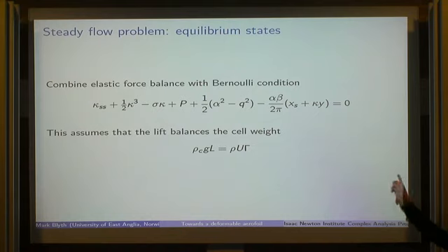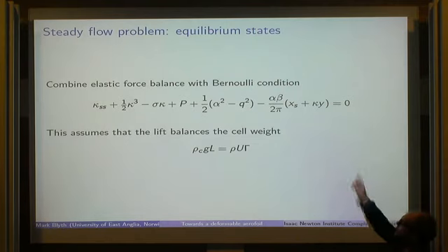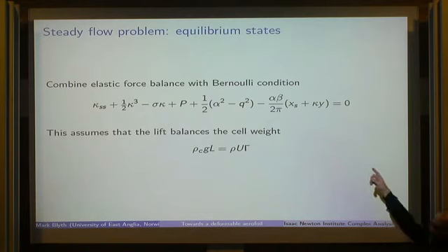So what I've done is taken the equation that I derived before and replaced p, little p, as a function of s, with what you get from Bernoulli's equation, fixing the Bernoulli constant at infinity in the usual way. And I've also non-dimensionalized. So that's the dynamic boundary condition on the cell wall, balancing the effect of the pressure force against the elastic forces. So which one is the velocity squared term? That's q. Q is the speed, so that's q squared.